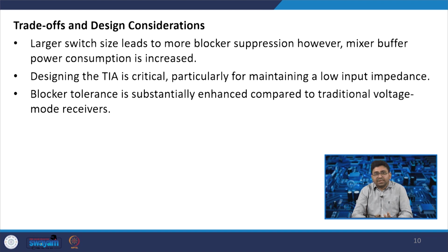So, while designing the TIA, it should be ensured that the input impedance is low, and which will be up converted at the input of the passive mixer.